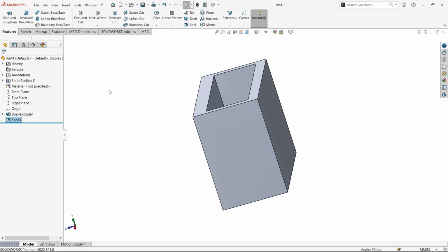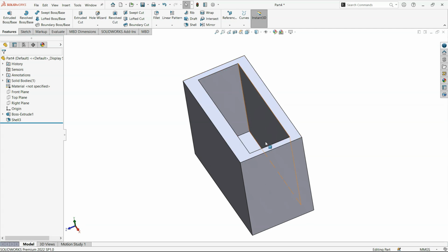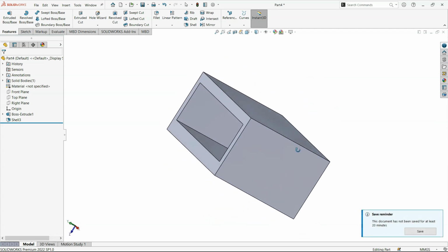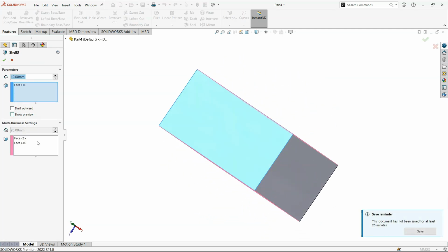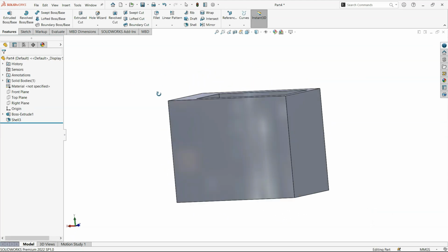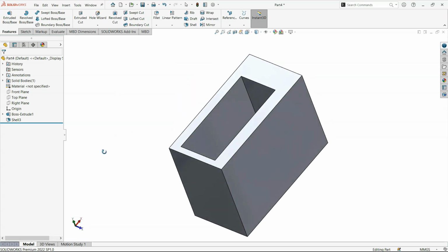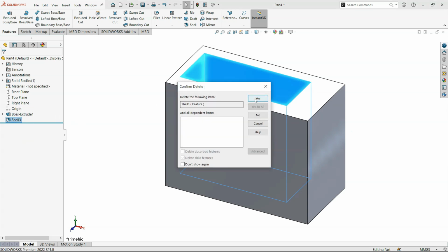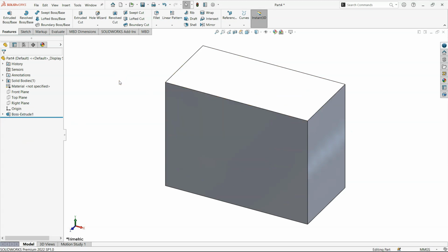Then I will just click OK, and you can see that the front face is removed. This surface has 15 and this has thickness 20. We can clearly see it. And let me select this and give it a dimension of 40. You can now clearly see what the multi-shell thickness setting can do, and it is a very handy tool. So now we have discussed the shell feature.